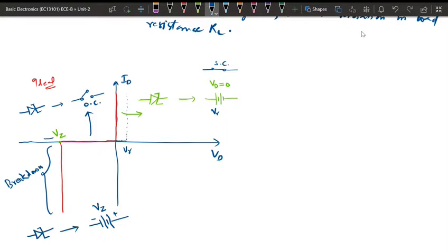That limiting will be based on power dissipation. The power rating of each Zener diode is given by Pz maximum. That means the maximum power it can withstand. If we go beyond this maximum power rating, then this Zener diode will get damaged. So we need to limit the reverse bias voltage so that the power stays less than the Pz value.